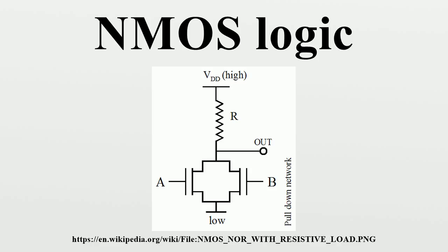Like other MOSFETs, nMOS transistors have four modes of operation: cutoff, triode, saturation, and velocity saturation. MOS stands for metal oxide semiconductor, reflecting the way MOS transistors were originally constructed, predominantly before the 1970s, with gates of metal, typically aluminium. Since around 1970, however, most MOS circuits have used self-aligned gates made of polycrystalline silicon.